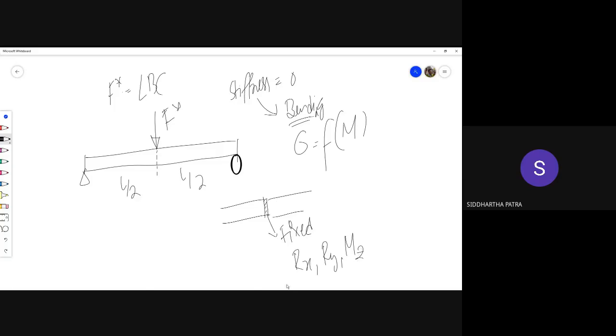Now in this joint, the moment bearing capacity is lost. It has become zero because the entire section has become plastic. Now it can support maybe Rx and Ry, but it can no longer support bending moment or any moment. So you have now a fixed joint which cannot support moment but only supports Rx and Ry. Then what sort of joint has it?